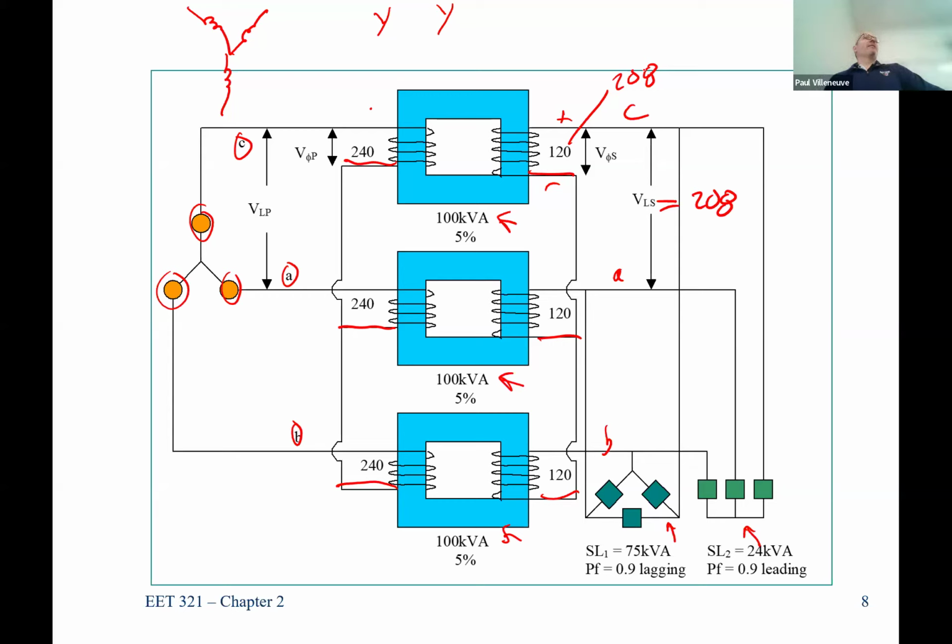Many dry goods stores don't have 3-phase because you just have heating and ventilation and lights. You don't need much power demand there. So unless you're like the size of a Kohl's, which is massive, you're most likely not going to need 3-phase power.